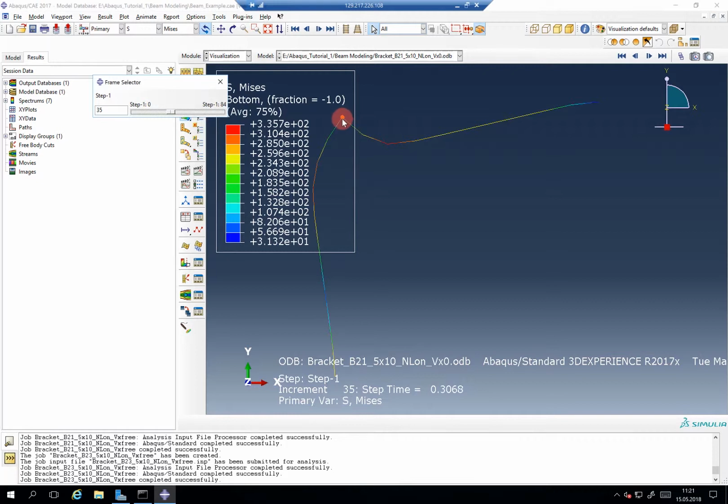If you want to have a special joint in here, you would have to model it differently. This is a more advanced topic. So don't get confused why this stays at 90 degrees. It does so because you're asked to. You can now also see that the elements stay straight, and this is the point where we applied the forces. So it was a distance of 20, the length 10 per element. So it was this point to which we applied the forces.